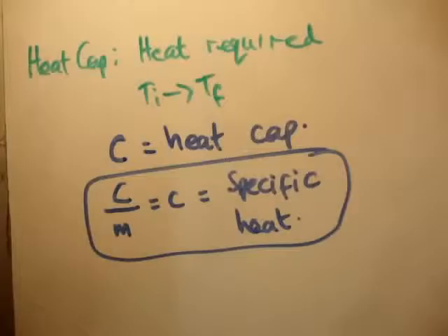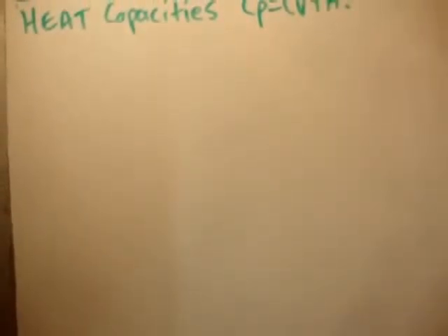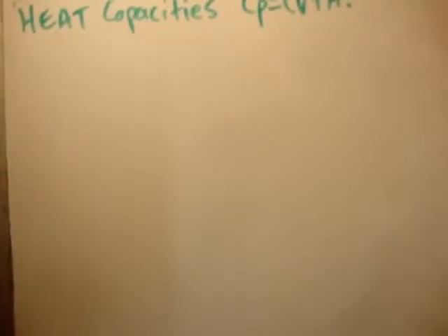If you're talking just about the heat capacity, it's very ambiguous. But if you're talking about the specific heat capacity, it is the amount of heat required in order to raise the temperature of one unit mass by a certain amount. That's really what it is. So that's what the heat capacity is. But we'll find out in a moment that there are two different types of heat capacity, depending on what the scenario is, or the way you actually put in the heat.